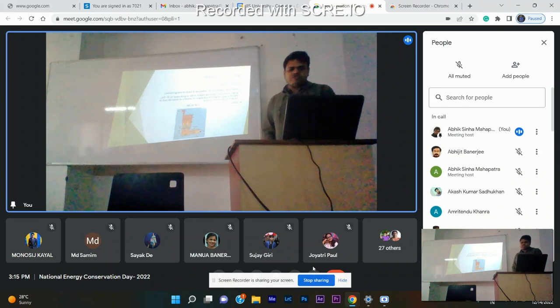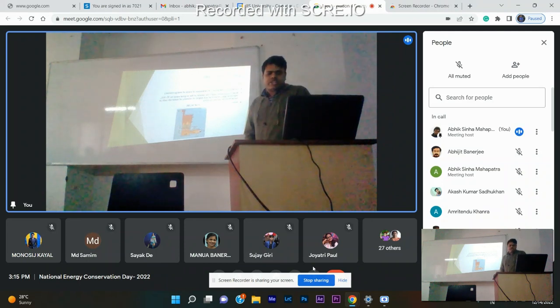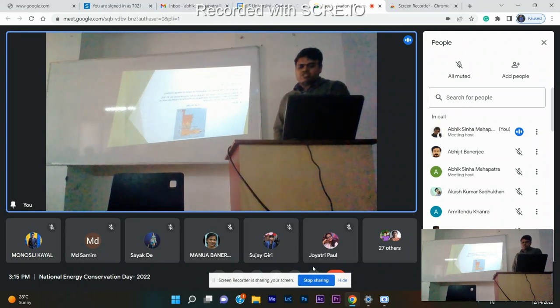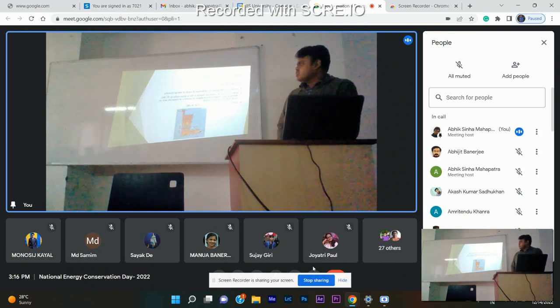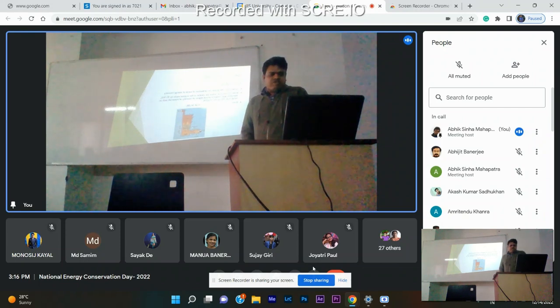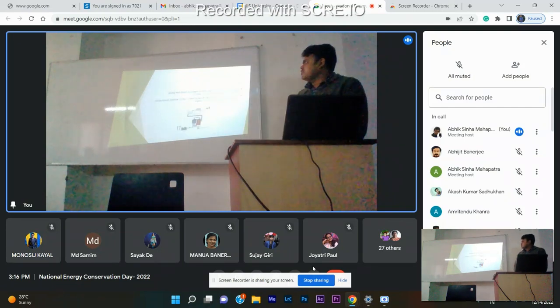There are a few types of technology to generate energy from waste. The first one is incineration. In this process, waste is converted for energy recovery, and it can reduce the volume of the original waste by 95 to 96%, depending upon the composition and degree of recovery of materials such as metals from the ash of the waste. It has an electricity generation efficiency of 14 to 28%.